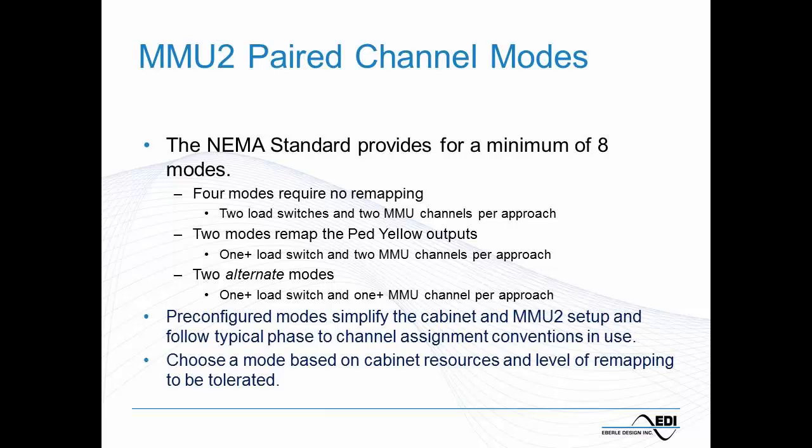So the way that we would normally expect a user to select a mode is based on what cabinet resources are available, meaning how many spare load switches do we have, how many spare monitor channels do we have to add flashing yellow arrow to an already configured cabinet, or maybe it's a new installation.